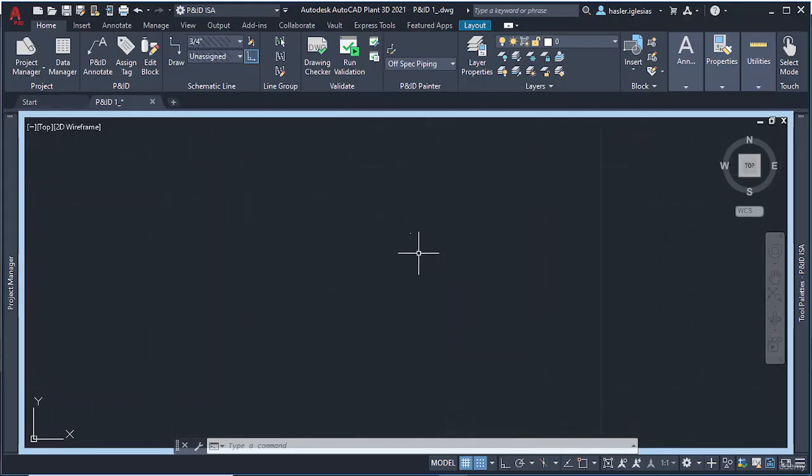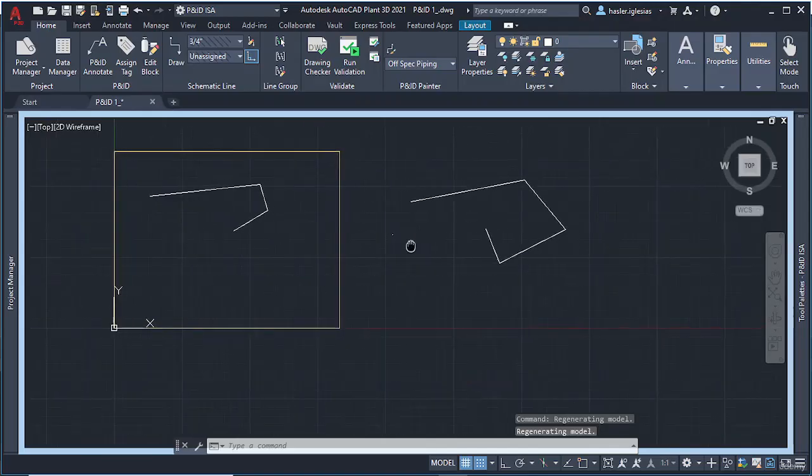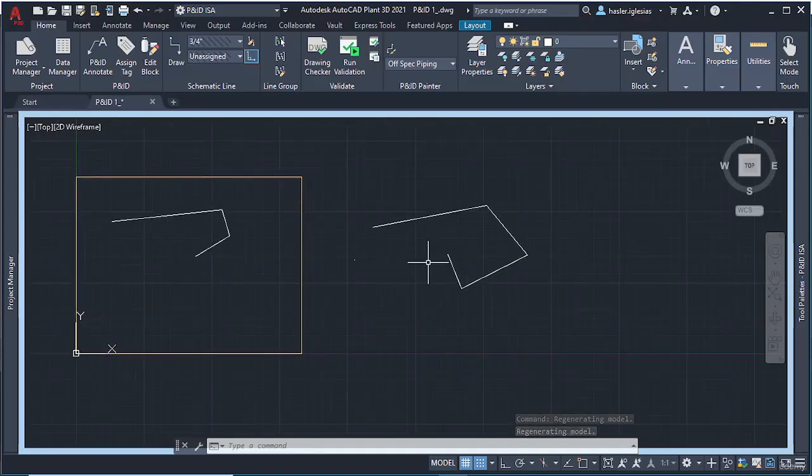I can zoom in as much as I want, and it will remain the same size because it's just a point. It can be annoying sometimes, but let's see a use. Let's say I need a circle, but I want it to be centered in that point. And for some reason, AutoCAD doesn't let me do that. So I can activate the snap here, and I'm going to write circle, and then specify center point. I'm going to approach the point I have just drawn.